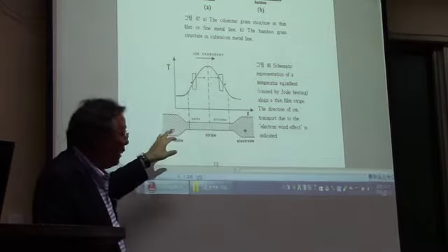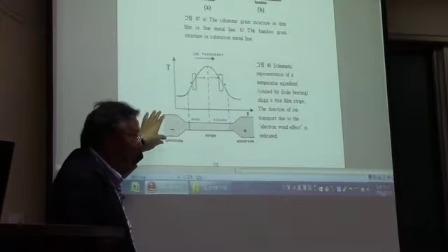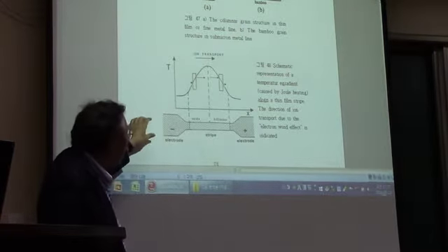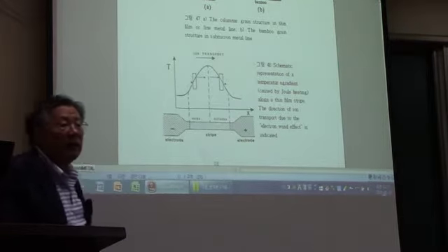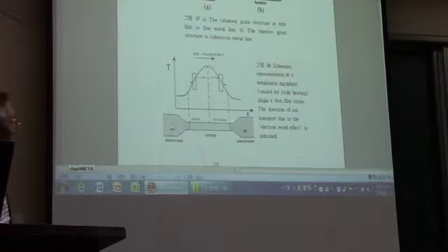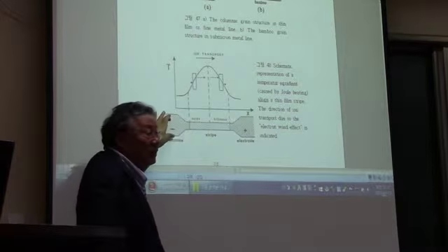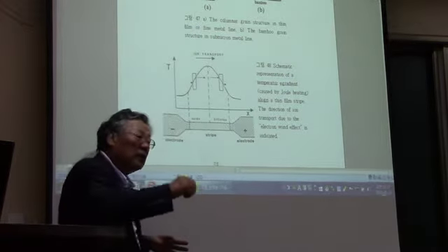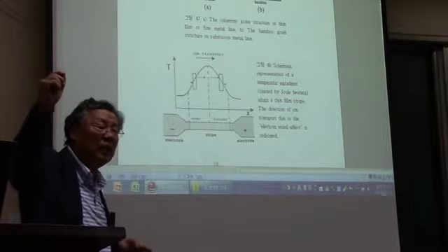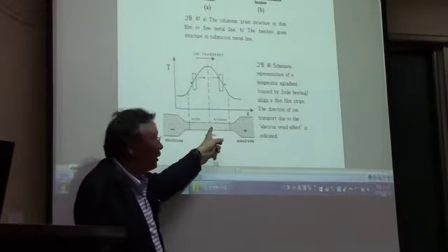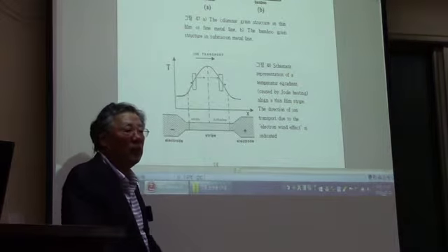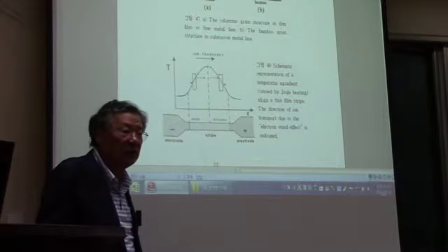And this can happen in VLSI if you have different widths of the metal lines. If you have a large area of the metal lines, then the heat is going to be dissipated into the air more than at the center, if the heat comes from the silicon substrate.